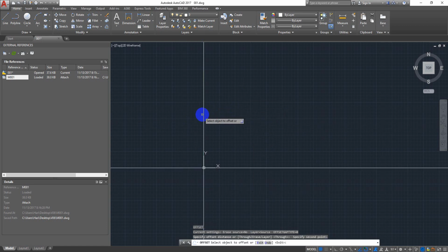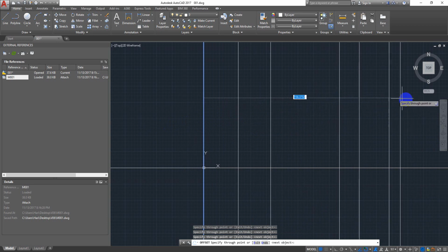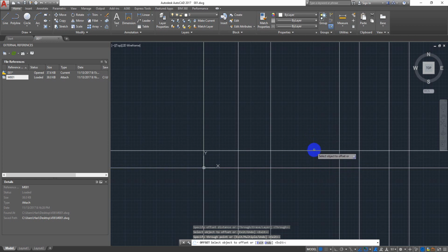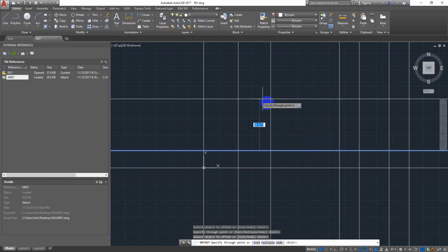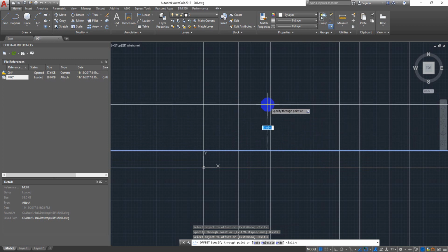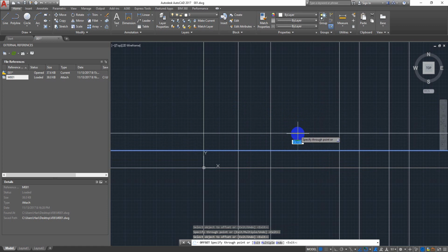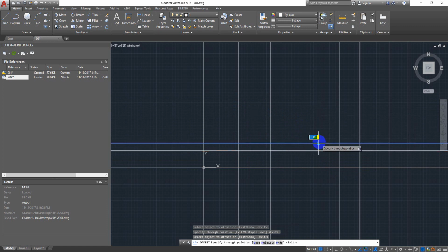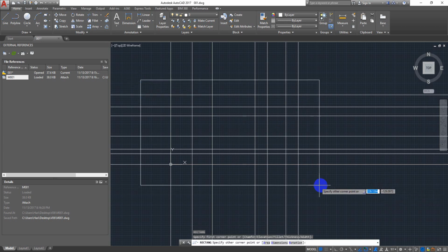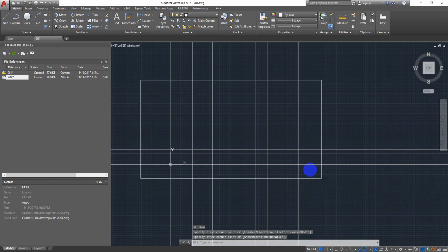Then from here you start putting offsets through multiple. Like this you can start putting your vertical grids and horizontal grids also. You can put them towards the positive quadrant. Always try to keep this on the positive quadrant. I am not getting into what quadrant and all; I assume that you already know about it. Like this you can start putting your grids. So this is how you should be creating the grid file. And let me quickly trim this so that I can show a live example.